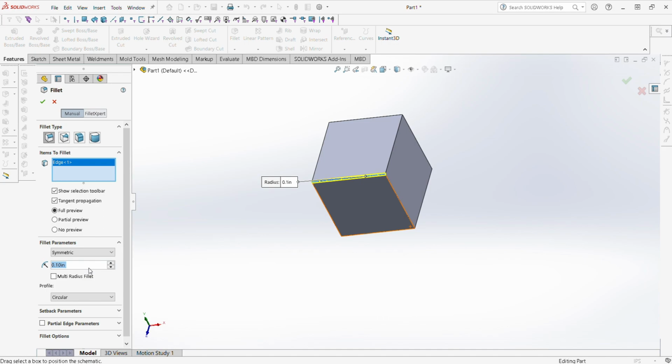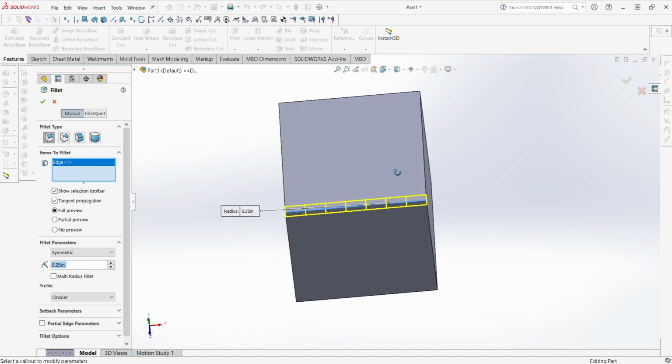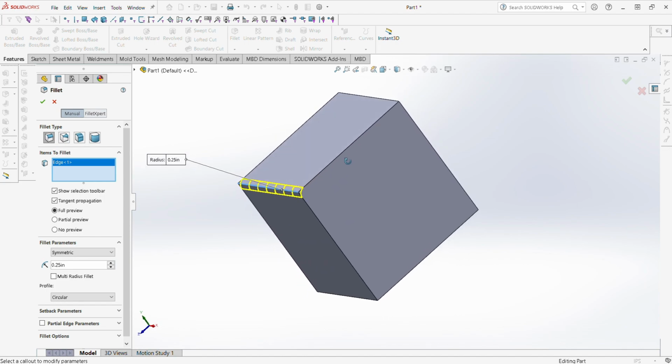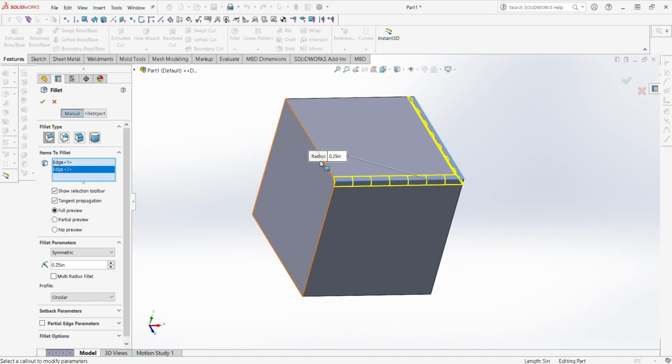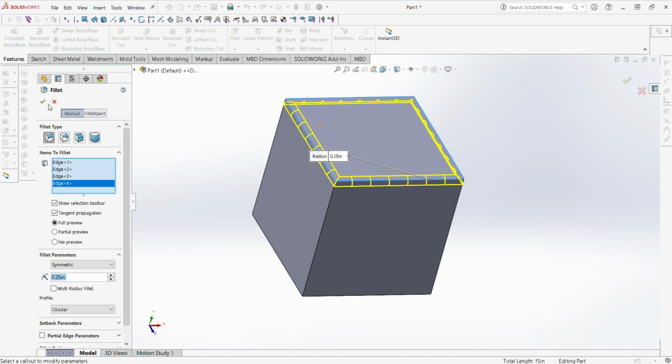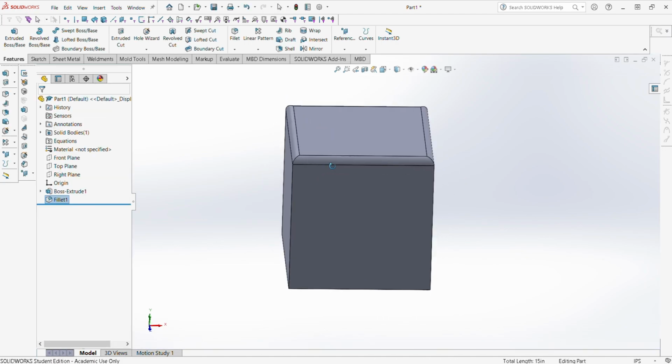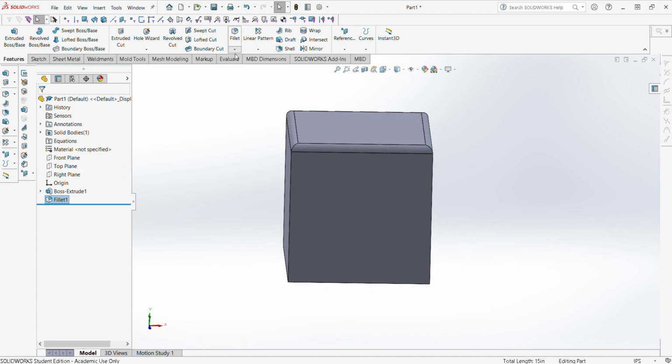Okay, we pronounce it as fillet, and I think that's just to make a distinction between the entree or the cut of fish and the round feature in CAD. A lot of other software just calls it a round, so I don't know what SolidWorks is doing, but yeah, this is a handy feature. If you're just trying to break a corner or something, you can also use a chamfer. Same kind of deal. It's just flat.